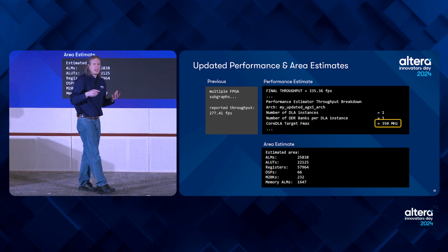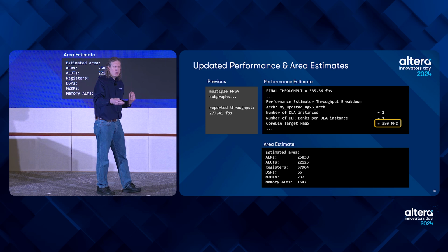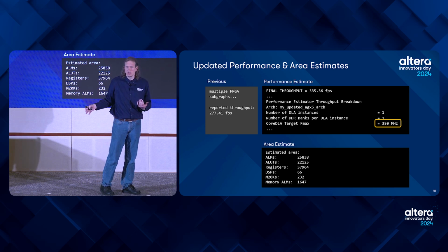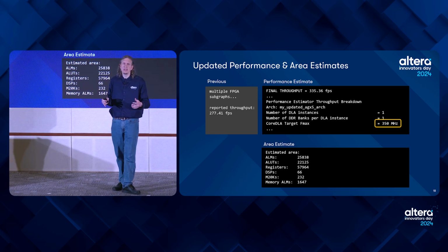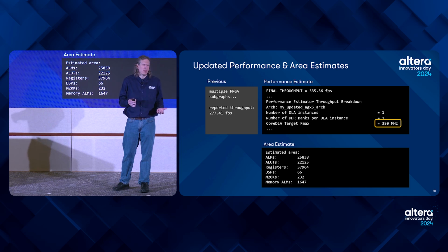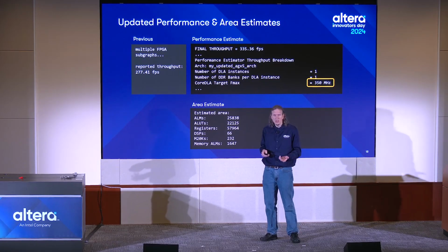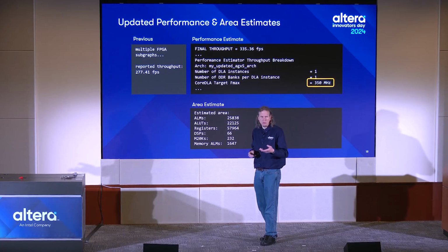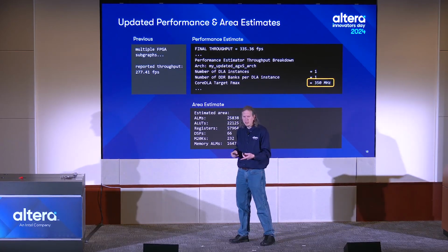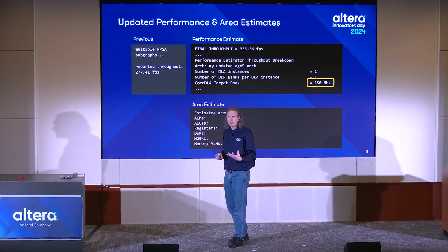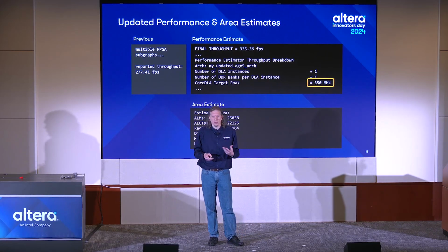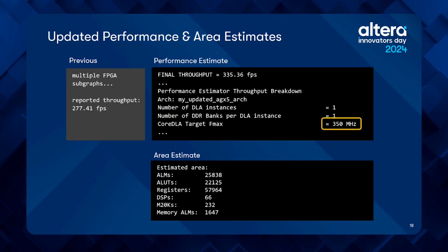If you have attached external memory, or if you have an attached host, then either of those could create an additional bottleneck on the performance that might result in sublinear scaling. However, in the case where neither external memory nor the host is used, the performance of the IP will scale linearly with regards to the Fmax.